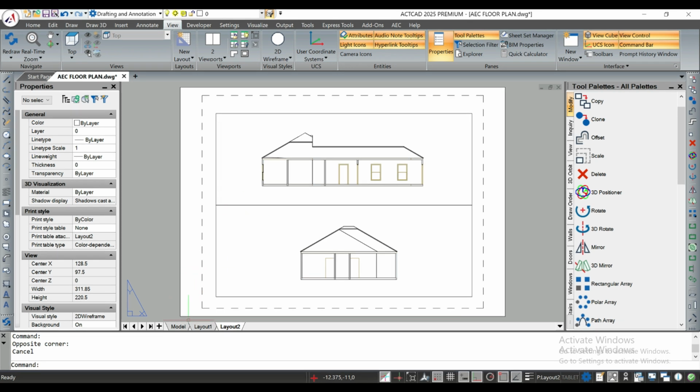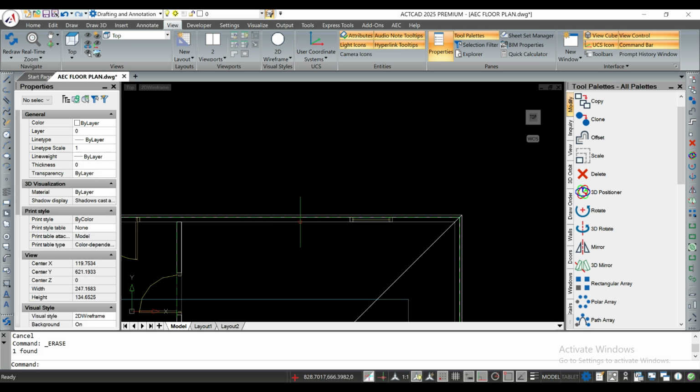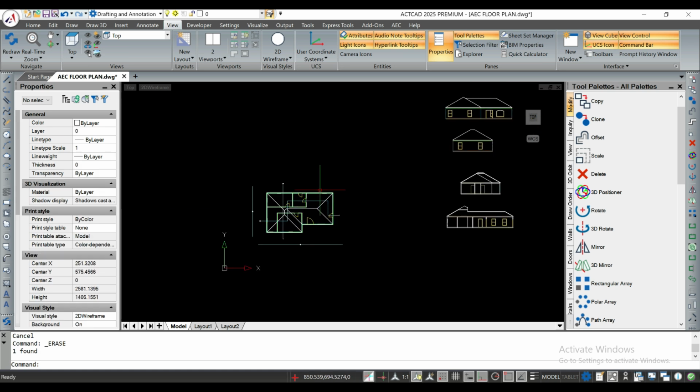As you know, things change. So, what happens if there's a change in your model? Our top section view is looking at the 2 windows on the back of the house. So, I'll make a change there. I'll go back to Model Space and delete the window on the left. As you can see, the window I erased is still there.